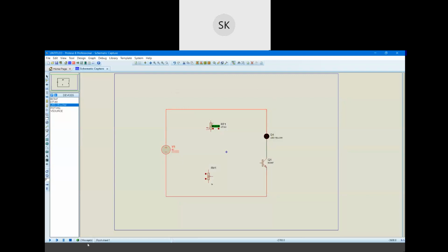Okay, again the circuit is not going to run, right? Because there is nothing connected to base. So what we have to do, we have to connect that sensor so that the current will also flow through the base terminal. And how much do we want? We want only up to 0.7 or 0.8. So we are going to connect it to that thermistor and also here.